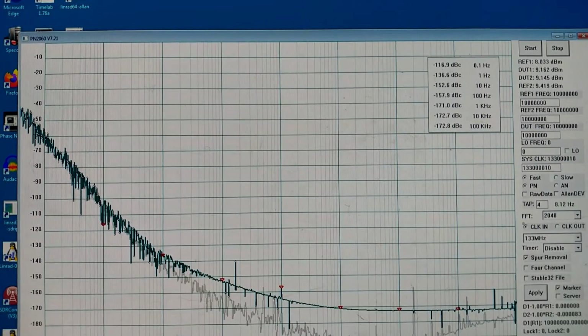So rather than having 3 kilo ohms from the crystal filter, I could transform it downwards to 1/4 of that and not reach as low as this, but a little bit lower. That would degrade the noise at wide range by 6 decibels, and for the purpose I'm looking at, it might not be harmful.